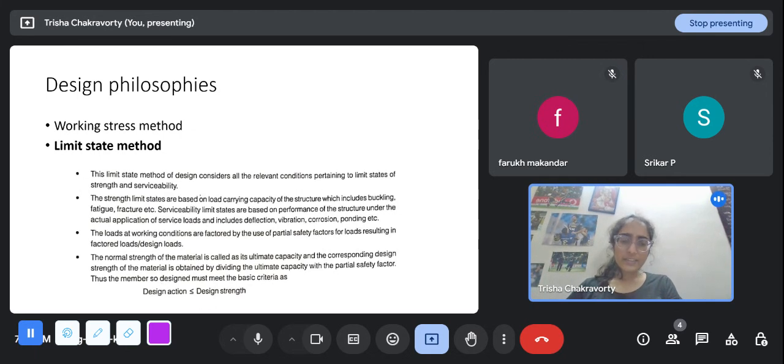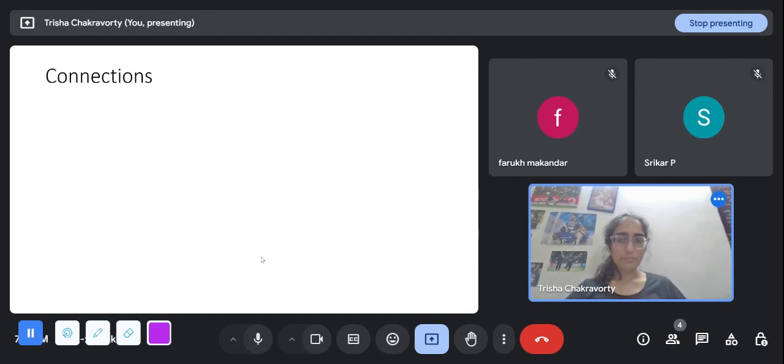And the design strength is got by the strength of the section divided by some value like 1.1, 1.25, so that we don't utilize the complete strength. We would expect a lesser strength than the complete capacity to be developed in the section. So both these partial safety factors lead to safer design. The higher the partial safety factors are, the safer the design would be. But again, it would start becoming uneconomical. So we have to strike a balance between the two.